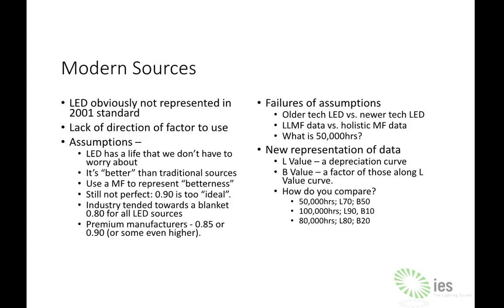That's interesting stuff, because they're trying to set their product apart from others. And this is how they can say, we sell quality LED chips compared to theirs that don't. That's part of the failures of the assumption that we're comparing old LEDs versus new LEDs with maintenance factor, but we're also comparing good LED chips with bad LED chips. And all this data that we're being thrown, this 0.8 and 0.99, that's still just the LMF data, but we keep sticking it in as our holistic maintenance factor. When a manufacturer says 50,000 hours, 58,000 hours to what?